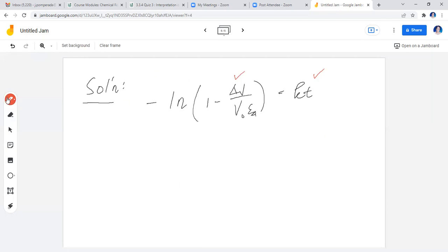I intentionally solve this problem last because this is easier than the first one. Whenever a problem for varying volume system mentions that your system starts with the pure reactant, meaning there are no inerts, the process of determining the fractional change in the volume is even simpler.